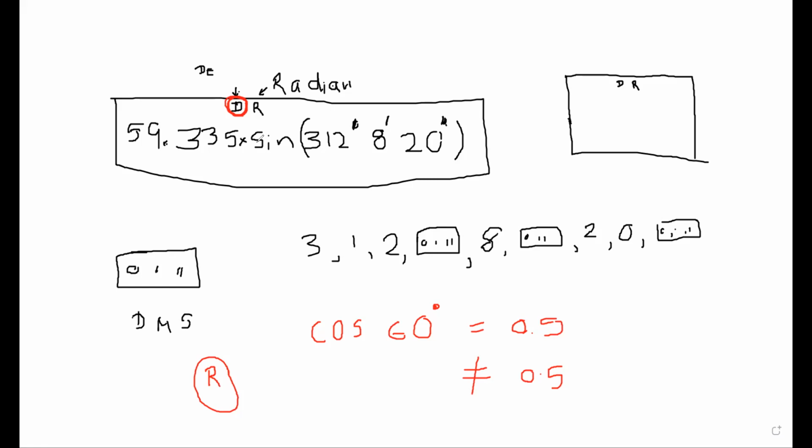And do that for all the lines. Never mind how many lines you have, if you are moving in sequence, going round in order, you will get all these delta E and delta N simply by these two equations, L sin phi and L cos phi.